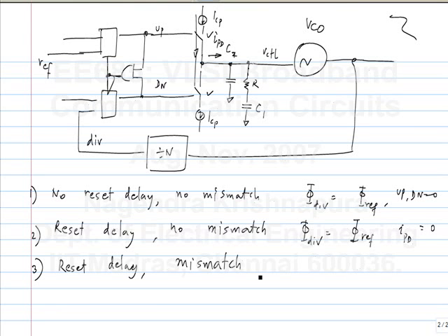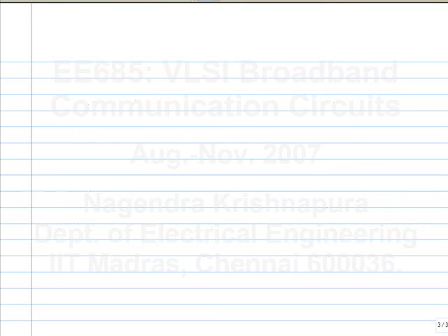Yeah. So what I was asking for was the operating point. So it's not really related to the transfer function of the VCO, right? So again, the steady state is when there is no long-term drift of the control voltage. That means that the average value of this IPD, lowercase IPD, must be 0. Okay. Now, let's say the up current is ICP plus delta I and the down current is ICP minus delta I, right? So what will be the steady state phase difference between A and B?